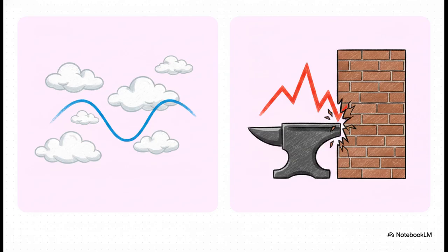But in a hard real-time system where failure is catastrophic, no way. You cannot rely on averages. You must base every single calculation on the absolute maximum time a process could possibly take. This is your worst-case execution time. So remember, know your strict deadlines, know your polling frequency, and always calculate based on the worst-case scenario.